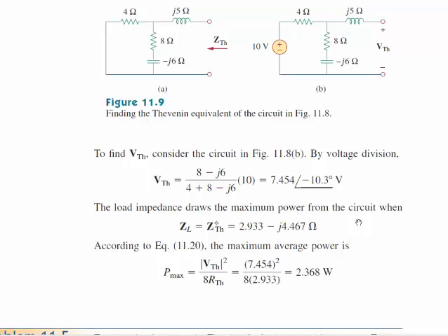So you can treat that sort of as a voltage divider, and you can find what the voltage is at these terminals with the voltage source, which is an AC voltage source, put back into the circuit. So then now I have V Thevenin and I have R Thevenin or Z Thevenin, and Z load has to be Z Thevenin complex conjugate. That's when the maximum power transfer occurs.